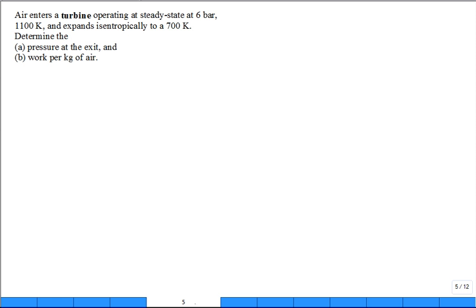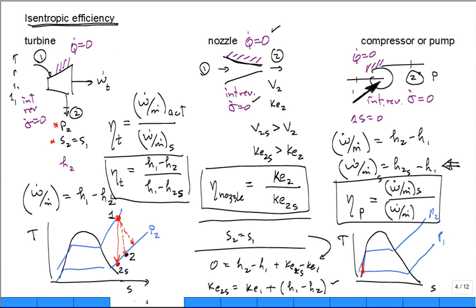Sorry, why is the isentropic efficiency... Yeah, that always will confuse students. Just think of this. Should that efficiency be greater than 100% or less? I know the COP, coefficient of performance, we let to be greater than 100%, like factor 2 or 3 for the COP. But here, you want efficiency, the isentropic efficiency, to be less than 100%.